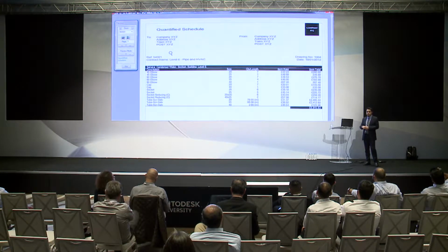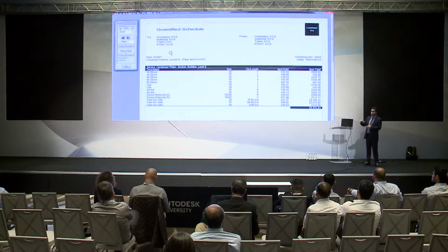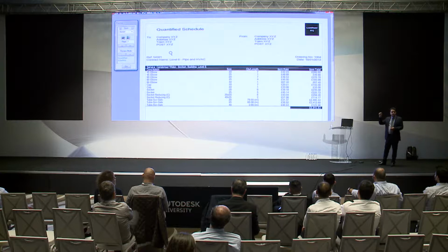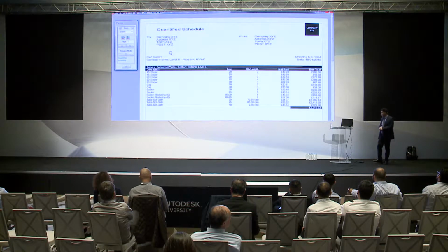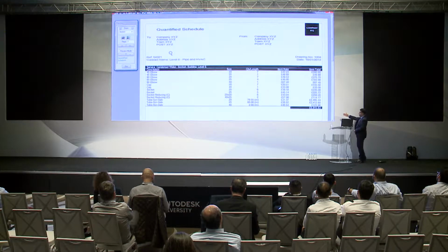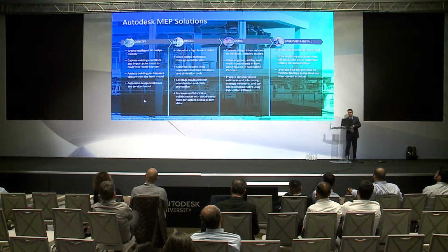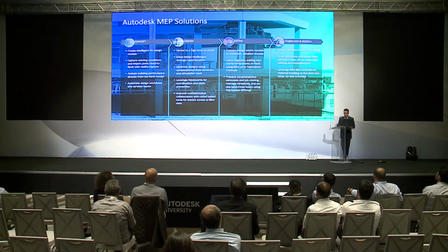If I have a particular size hanger, that will determine the size of the nut and bolt. Automatically, it will look at how many of those hangers I have in the project, and it will tell me how many nuts, bolts, and sockets I will need as per the requirement. So the costing will be there. The itemized list, everything is generated automatically from this location. That is the detailing portion, and that's the portion for the estimation also.